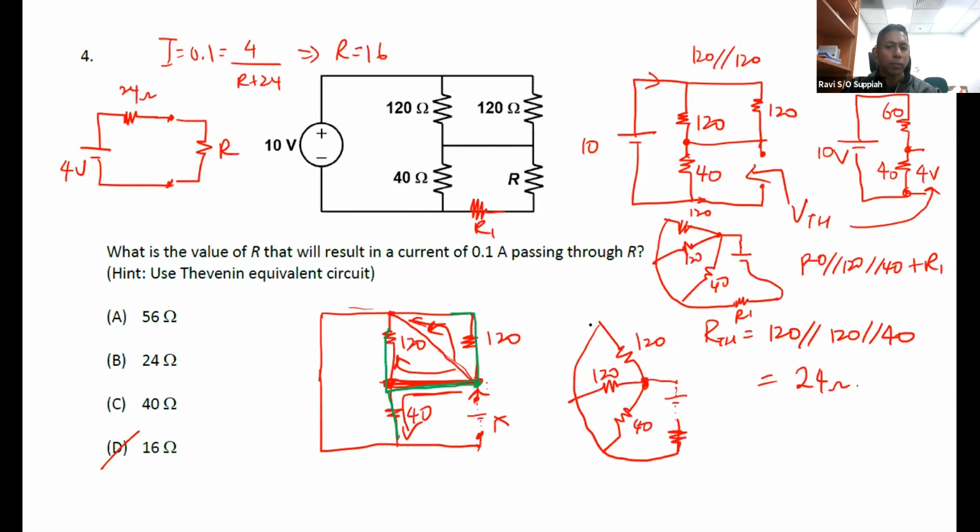If I have a short circuit pathway that's parallel to one of the resistors, then it is possible for me to ignore that resistor. Oh, I get it. Because right now, this short circuit is not exactly bypassing any resistance in that sense. Correct. Yeah, because there is no way for the current to skip any of this resistor. It has to go through everything.